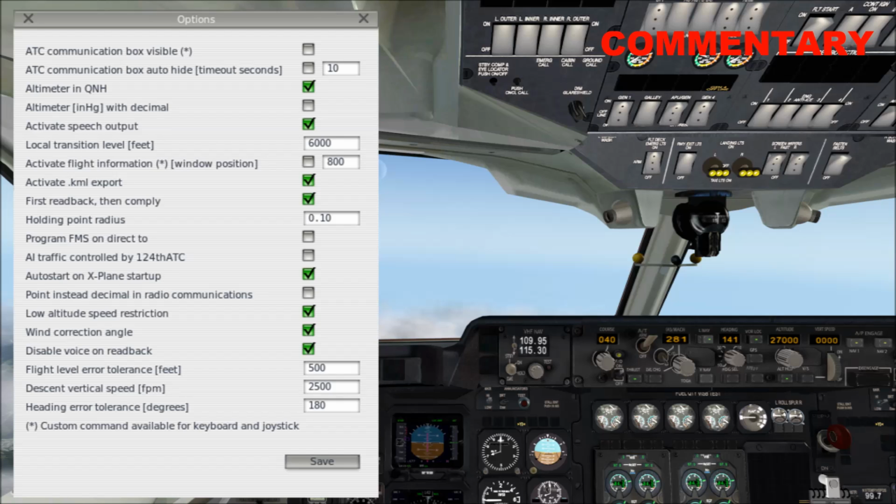Usually below 10,000 feet there is a speed restriction of maximum 250 knots. If you check this option, ADC will inform you in case you exceed this speed restriction. Depending on winds, the aircraft heading does not correspond to the really flown heading, and ADC would provide frequent heading instructions, even though you're already flying the correct heading. The plugin will consider winds for the heading instructions when the wind correction angle option is selected.